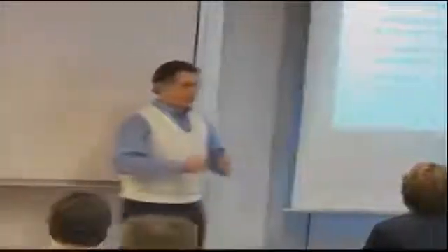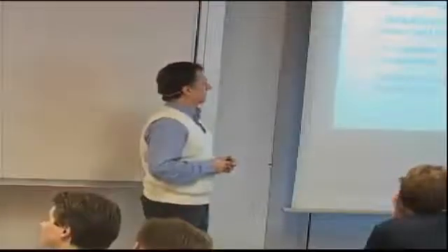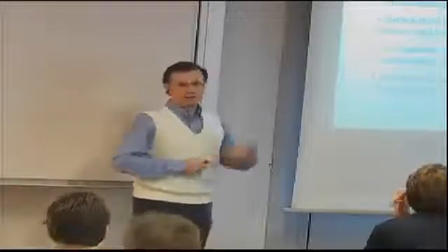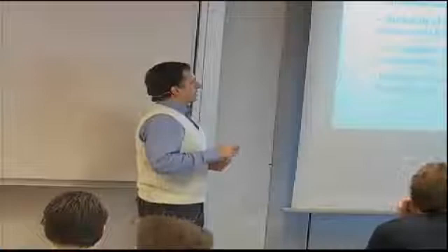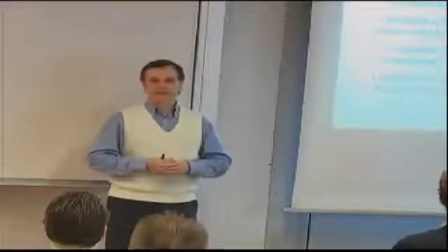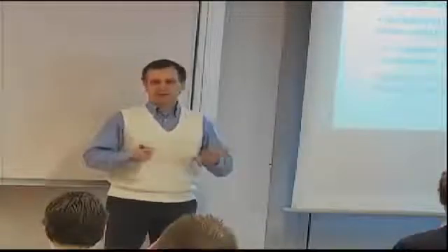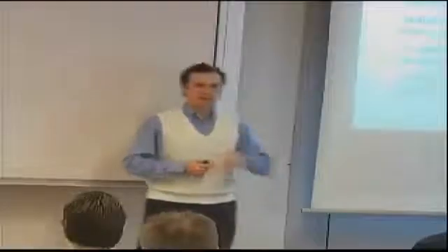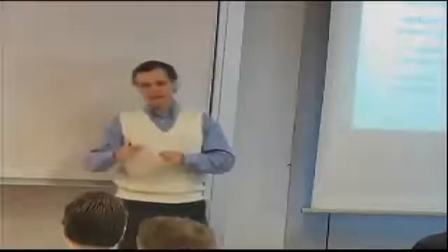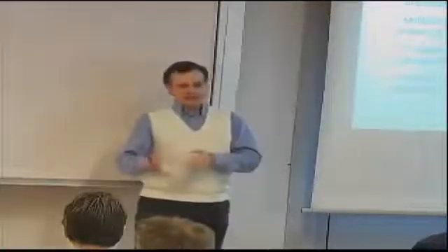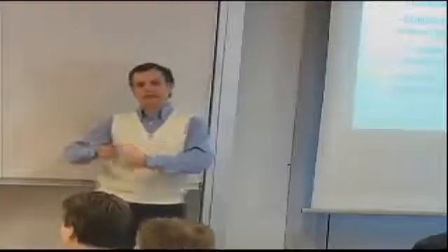And in general, today's lecture is finishing up on some things we started talking about in the design process, as they are more specific to composites, but they are general enough that it would be good to have in mind. And some of these aspects you will see in the homeworks and the final projects as we go through the course. Then we'll talk a lot throughout the course, briefly starting today, about the fact that a structure can fail in more than one failure mode. In the standard metal structures, you can have buckling or yielding, and you don't know in advance which is going to happen first. So in composites, it gets much worse. There's many more, and you can anticipate that by thinking about the fact that you have fibers and matrix, and either of them can fail, or the interface between them can fail, and then in sequence can trigger different types of failure modes. And that, as a result, would make it more complicated, more challenging, and more interesting.